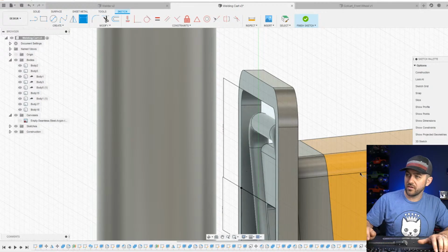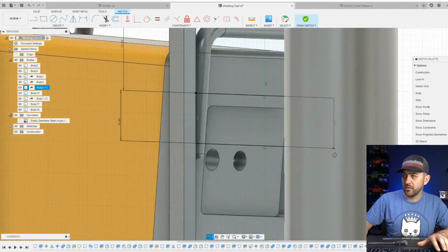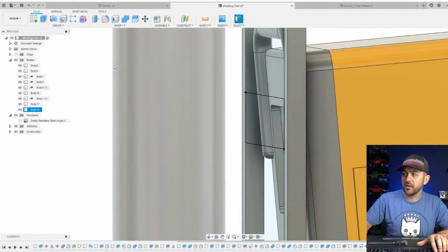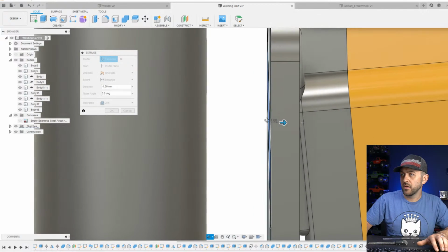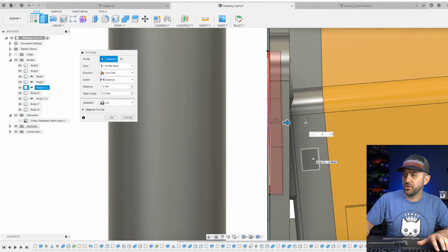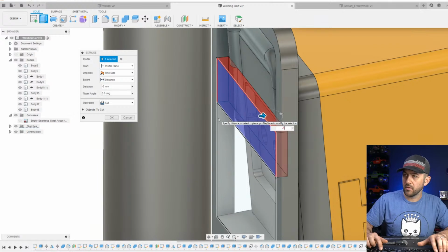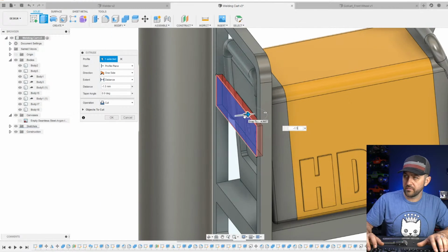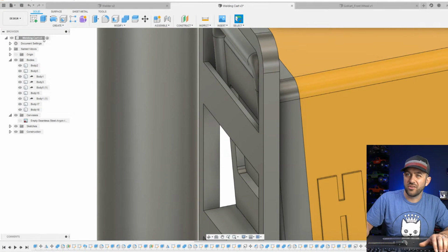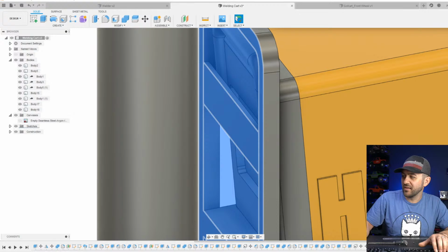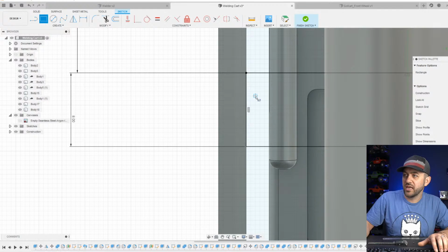Let's go. Okay, so we're going to do that, and it's still going to give us room for your power lead to come out. We're not going to have a lot of depth to offer here, but if we go -2, it does start to collide with the welder a bit. I guess we're just going 1 millimeter. That's really all you need. So we did that, but we need to add some slots for chain.